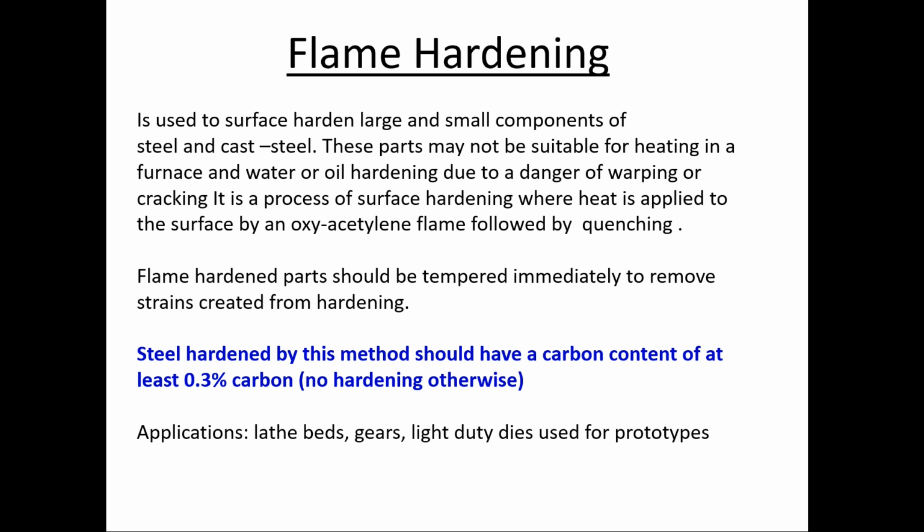Carbon is the basics, and then all the other things add to it. Carbon, and you add chrome to it, wow, you're really getting hard now. Drop in a little bit of tungsten, tungsten carbide, drop in a little bit of vanadium. Now it gets harder and harder. Now, you can get the carbon content in a material just perfect to the point where it's pretty tough. But if you heat it up to its eutectic point quickly and then quench it in oil or in water, you can make it so that the surface is hardened, but not underneath.